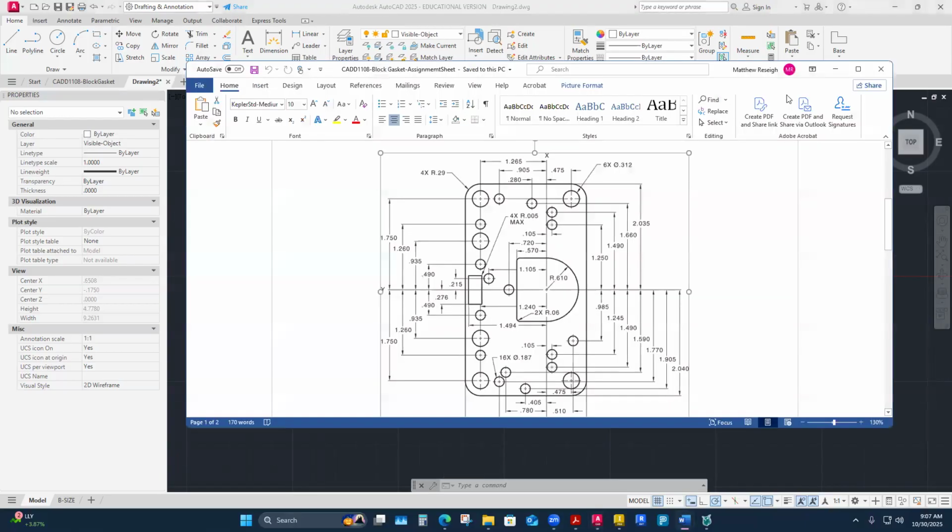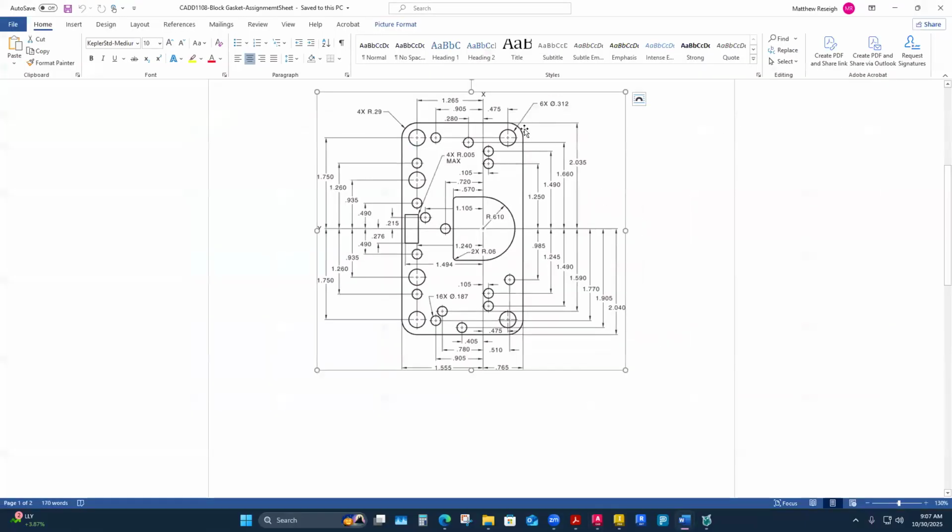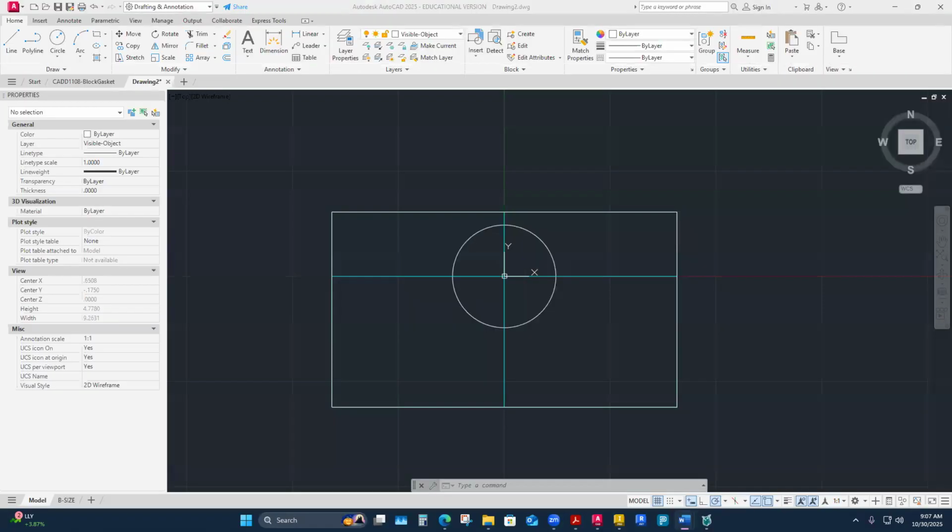I don't know for sure, but I'm not going to assume that the outer radiuses and the holes are concentric. I'm given dimensions for the hole locations, so I'm definitely going to locate these holes by these linear dimensions rather than just assume they're concentric. They may or may not be. I'm going to go off placing those from the dimensions given. I think it's made to be kind of painful to piece together, but that's what we've got to do.